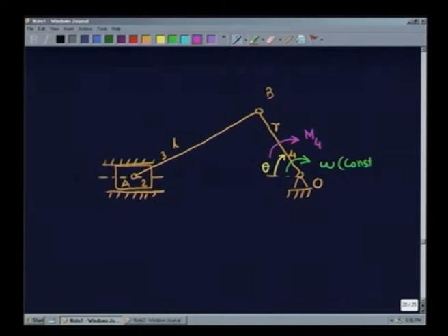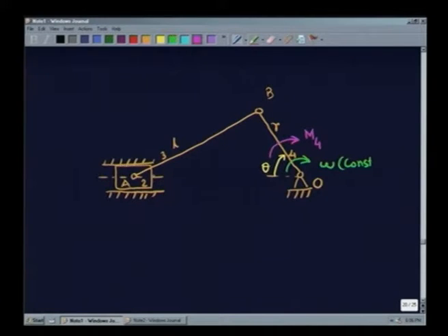Our objective is to find out the total force on this connecting rod. Why am I taking up this particular member? Because you will notice that link 2, the slider, executes a simple rectilinear translation, a simple form of motion. This crank executes a pure rotation with this as the center, also a simple motion, but this has both rotation and translation combined.